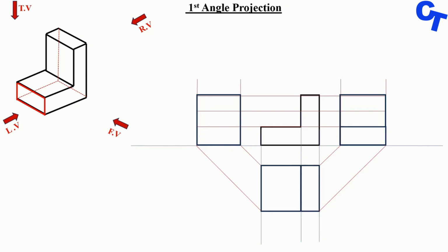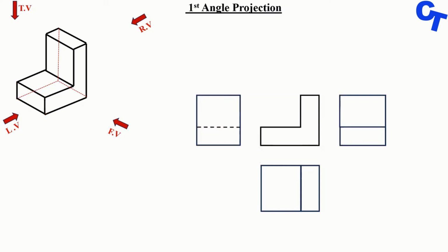So what do you do in engineering? That's what introduces what we call hidden detail. So now I'm going to put a hidden detail right there to show that there's a line right there, but we're not going to see it since it is going to be blocked by the profile on the right view, right? Okay, so now we have everything that we need. I'm going to show you the final look, which is right here. So this is what we have. So this is orthographic projection.